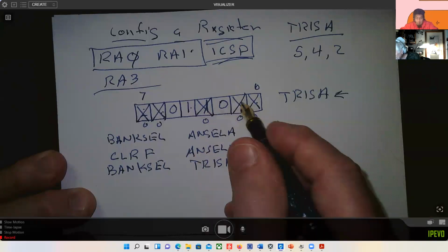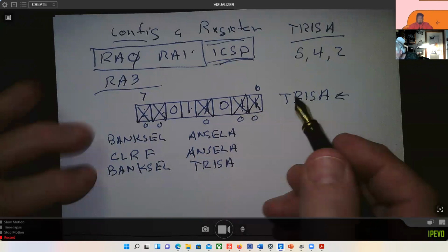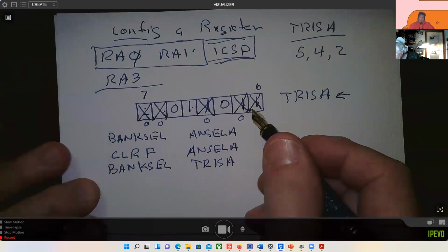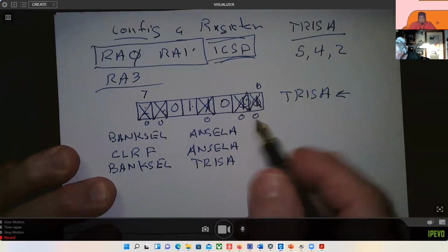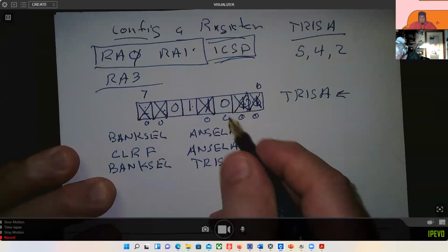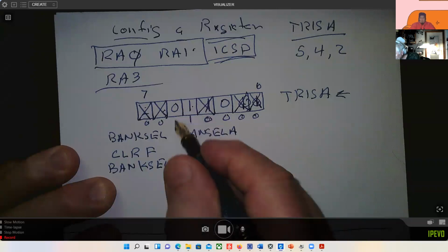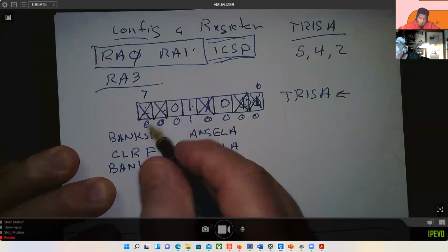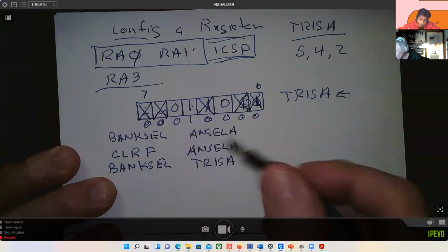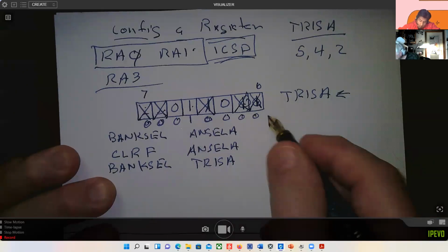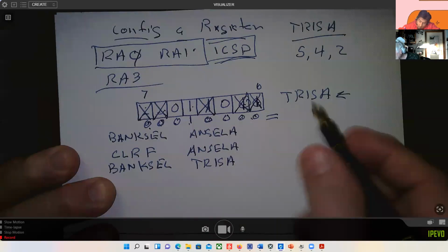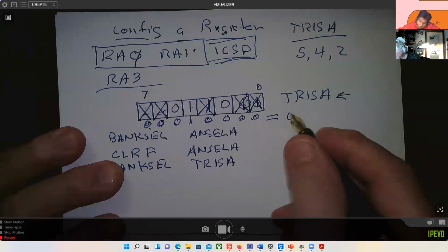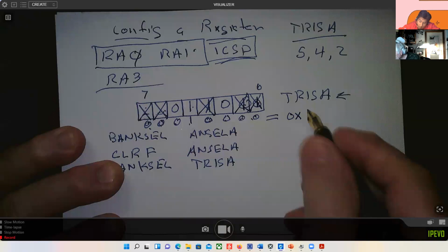We'll write 1s in here. What the heck? You can write 0s if you want. It doesn't really matter. Maybe I'll just make them 0s. Okay, so that's going to be 0, 0, 0, 0, 1, 0, and then we'll put 0s up here. Again, not implemented, really doesn't matter. So now I translate this 0, 0, 0, 1, 0, 0, 0, 0 into 2 hex digits, 0x10.